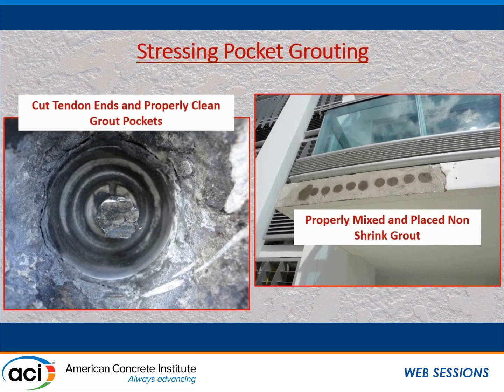The photos up there now are of this structure. This was the investigation that was done about 3 years ago, which led to a large settlement. Now the project is to do a bunch of waterproofing and a lot of other architectural applications, but this is opening up all these pockets, and the tails were not cut to the 3/4 inch length that they should be. Some of them were right at the surface, some were a 1/4 of an inch in, and so you have to go in there and trim all of those, clean them, and then repack them.